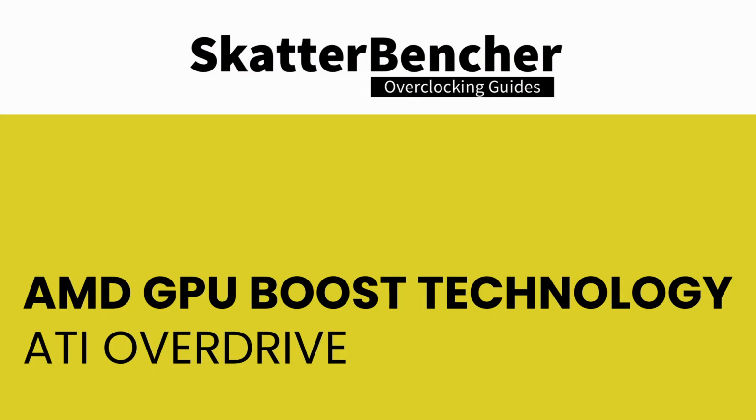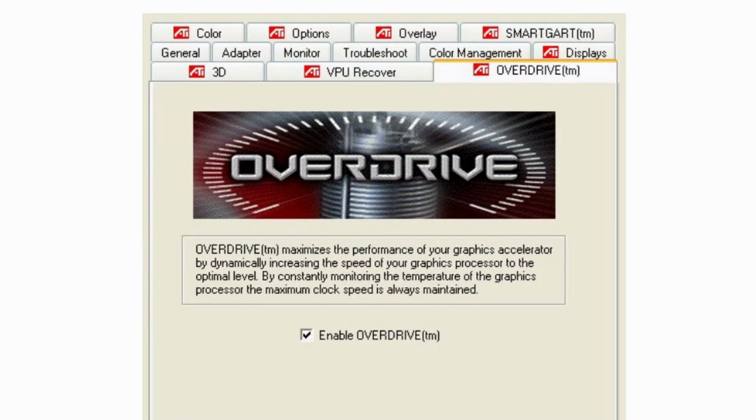Another feature that AMD added to its portfolio when it acquired ATI Technologies in 2005 was Overdrive. Overdrive was a new feature that was added to the ATI Catalyst 3.8 software alongside the release of the ATI Radeon 9800 series graphics cards. Its function was pretty simple. If you enable Overdrive, then the GPU frequency would increase from 412 MHz to 419 MHz if the GPU temperature is below 56 degrees Celsius.